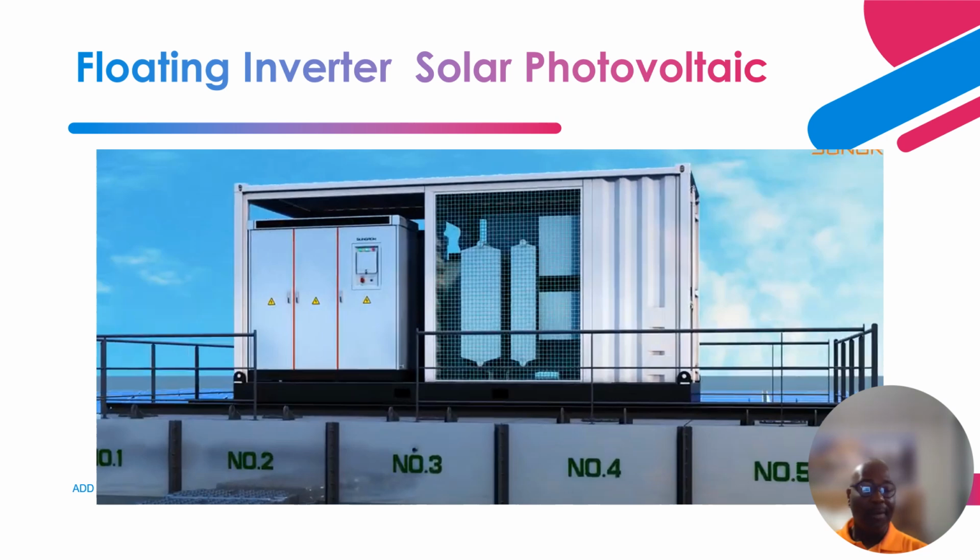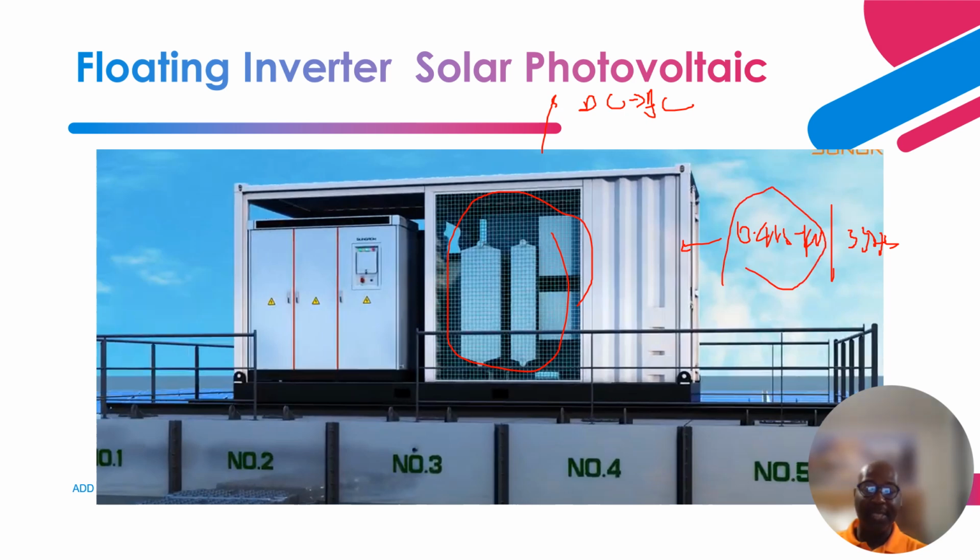Okay, so this is an example of the step-up transformer, the inverter rather. What is the function of the inverter? The inverter helps to invert the voltage from DC to AC, right? Before that, you have this integrated transformer that helps to step up the voltage to about 33 kV. The voltage that is here is about 0.415 kV, and it comes to this step-up transformer that steps up the voltage from 0.415 to 33 kV.